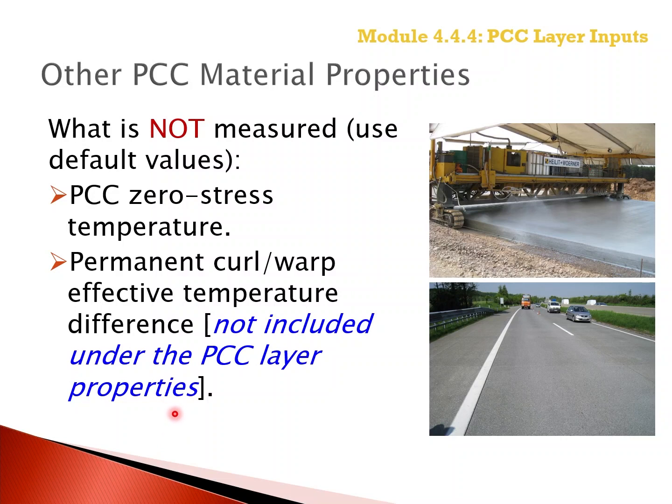The PCC zero stress temperature is the PCC temperature when the PCC mixture sets. In other words, the temperature at which no tensile stresses occur in the PCC slab without any wheel loads applied to the surface. No curling of the slab occurs.